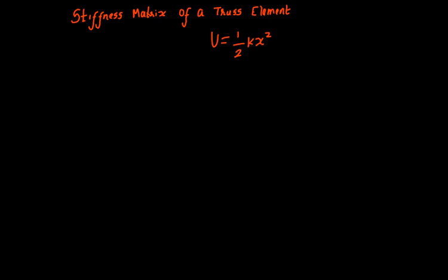All right. Now, without further delay, let us start the derivation for the stiffness matrix of a truss element so that we can do some wonderful analysis. As I said earlier, a truss is a collection of bars. A truss will not bend, guys. It's not going to undergo any bending. You would have seen truss structures in airports, and they are actually made of pin joints. Pin joints allow rotation. However, one member is preventing the rotation of the other member, so trusses are not going to bend. All right.